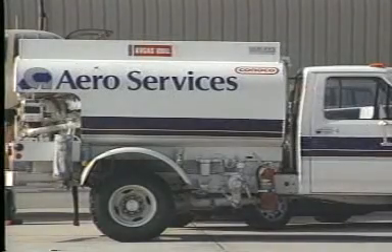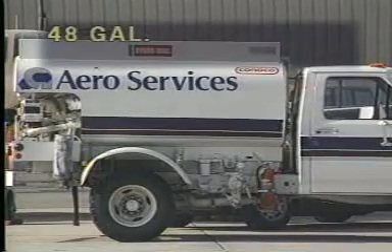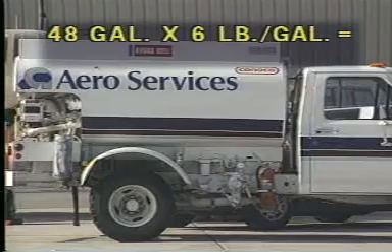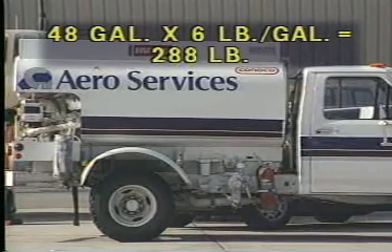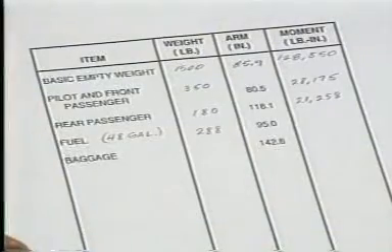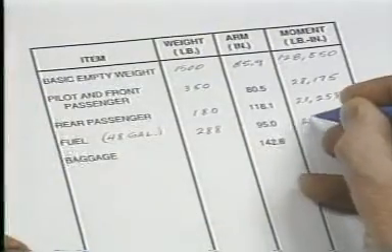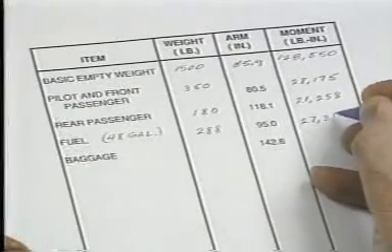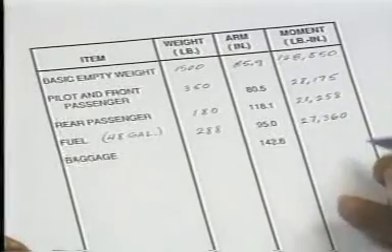The next major item is fuel. Since you intend to carry the maximum amount of usable fuel, which is 48 gallons, and since each gallon of avgas weighs 6 pounds, the total fuel load weighs 288 pounds. This weight times the arm of 95 inches yields a moment of 27,360 pound-inches.